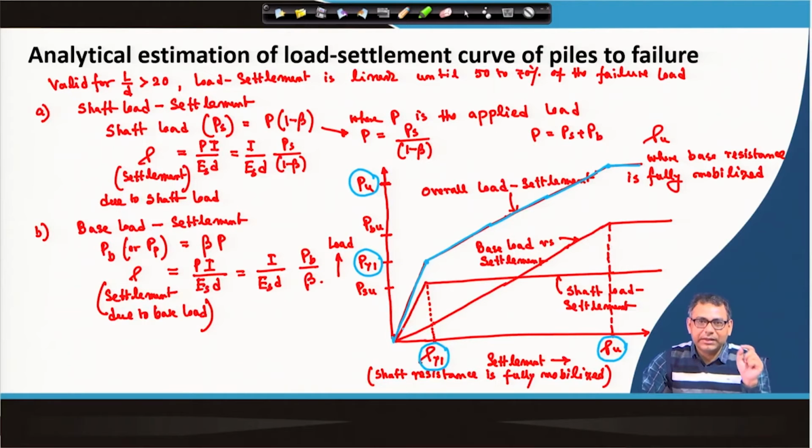Okay. So, remember that once the settlement of the soil is completed, the settlement of the pile material will start. That means the settlement of the soil will be completed at the end of the full mobilization of the base load. Okay? So, after that the settlement of the pile material will start. So, even the total tip load will not create an effect on the pile material settlement, because of the load which is transferred during the full mobilization of the shaft.